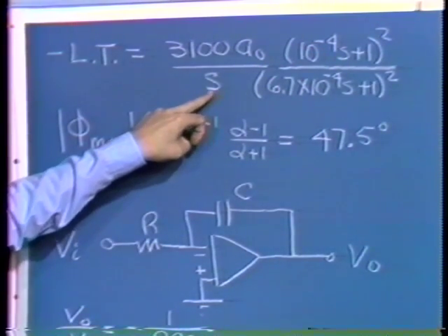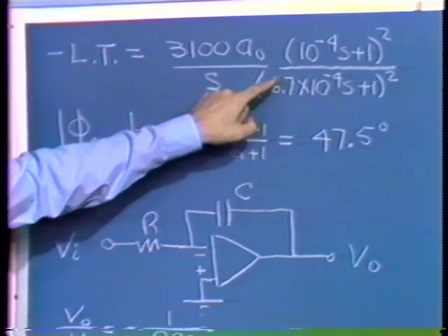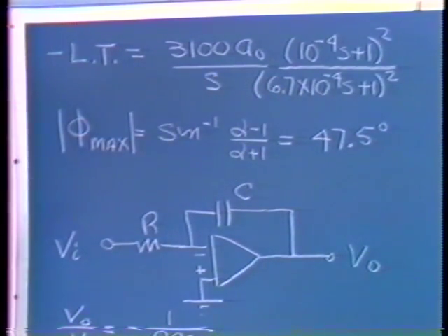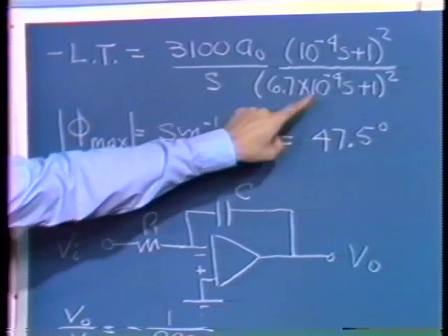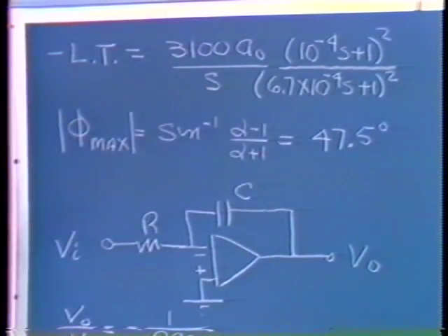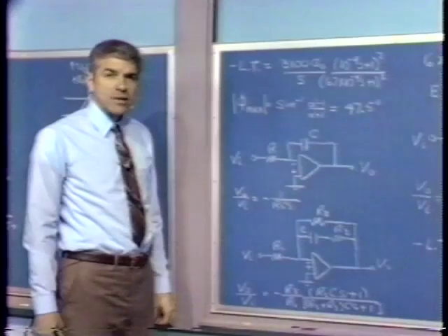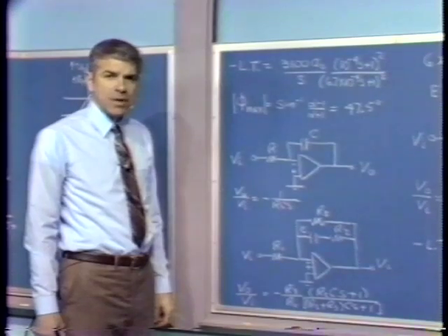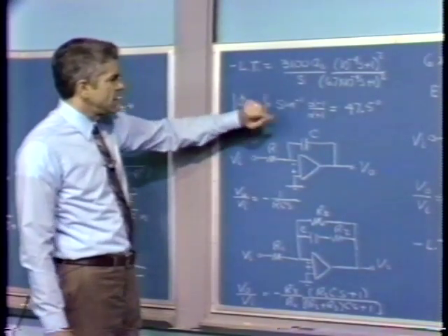This differs just a little bit from the description I gave earlier, where I assumed three coincident poles, but that's not a fundamental difference. Here we have one pole at the origin, two poles that are coincident further out, and as I say, then the two zeros. This is a system that will, in fact, exhibit the kind of angle versus frequency characteristic that I indicated characterizes conditionally stable systems. The angle will drop more negative than minus 180 degrees over some range of frequencies, and then recover to a value that's more positive than minus 180 degrees. We can see that pretty easily.